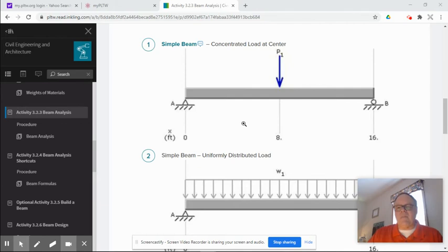for this beam. This is a visual tool, a graphic solution rather than a formula-like solution, that appeals to a lot of students, because not only is it easier just to draw it, but it also gives you a snapshot, or an x-ray vision, of what's going on inside this beam. You know exactly where the high shear is and exactly where the high moment is just by looking at the picture. So let me go show you the example for these first two.